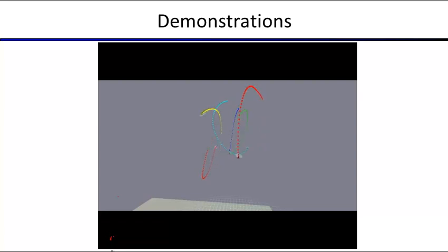It's just not exactly in the same spot every time, because that's very difficult. And if you look at this, we don't really want to fly one of these. What we want to do is fly something that's better than any of these 6. So think of these 6 as noisy versions of what we really want to do. Let's denoise these 6 and get out what we really want to fly. That would be our target trajectory, and then the reward function would just penalize deviating from this target.